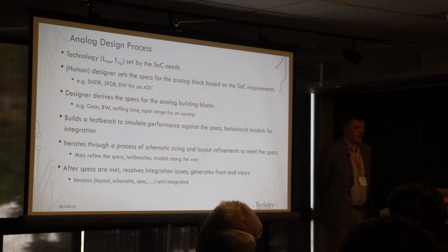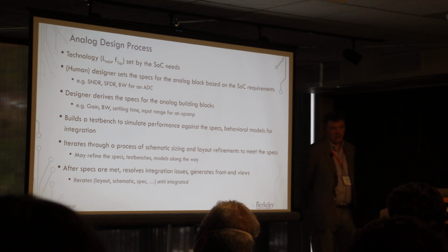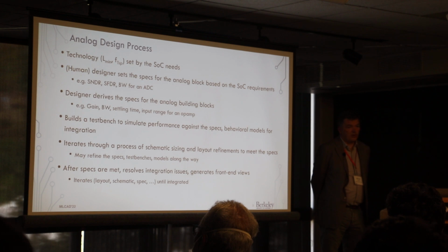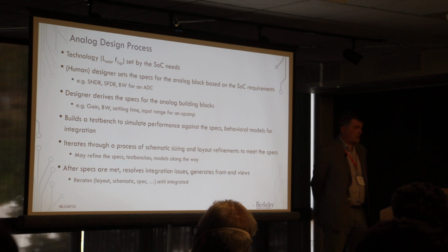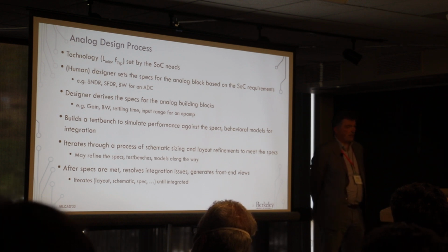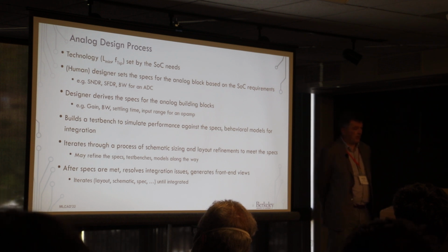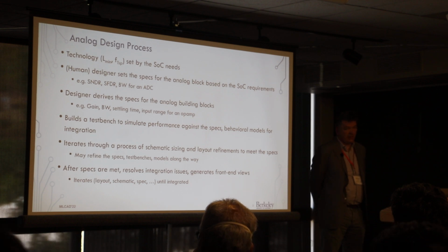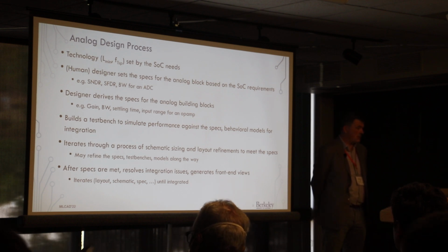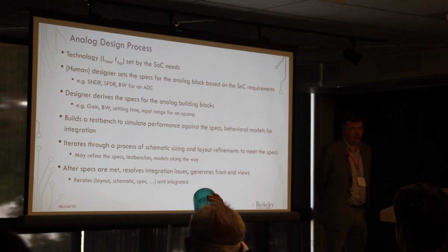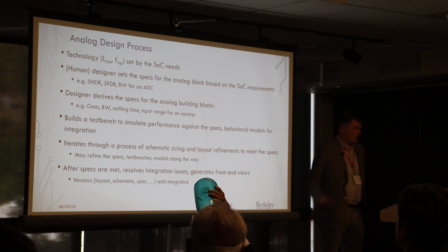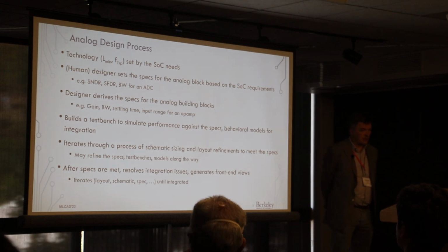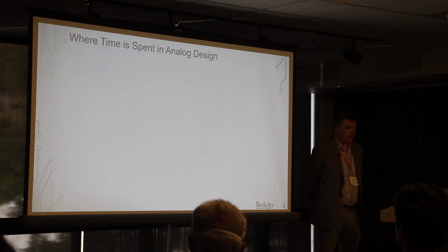Then they start iterating through a process of schematic sizing for that block. Say if it is an op-amp, they need to pick the sizes of all the transistors and capacitors, as we have capacitor resistors and bias points and so on that have been mentioned earlier today, and refine it in the process of running simulations by updating the test bench and going back to the layout and fixing things there. Then, after the specs are met, that needs to be integrated, and that changes things often because things might not have been envisioned early on. How are they going to fit in the final design? And they continue iterating through that process. That is often a pretty lengthy loop to close the design.